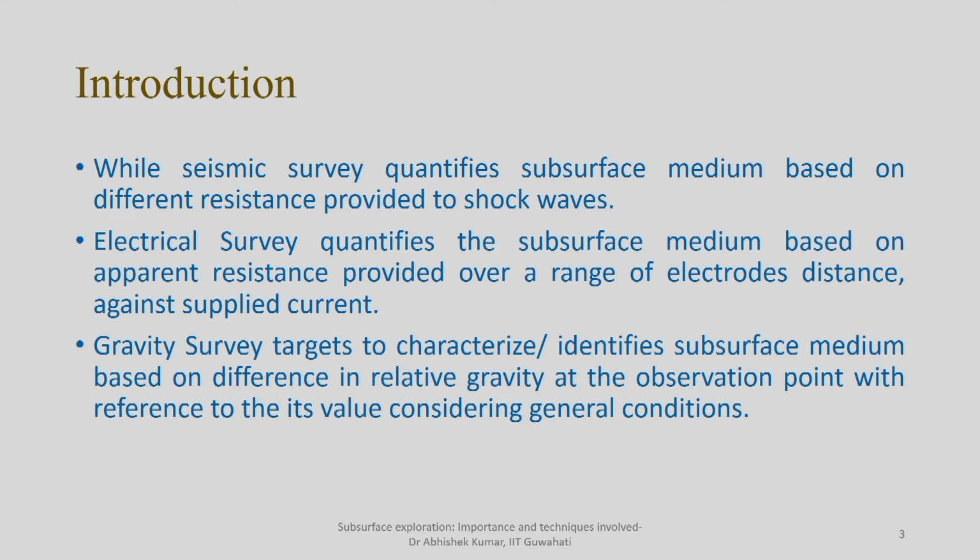Most of the time there will be a difference because the general understanding about gravitational force along the earth's surface does not consider site-specific or region-specific changes in subsurface medium characteristics. So, gravity survey targets to understand this change in gravitational force existing at the site of interest, and this change will be there because of change in the subsurface medium.